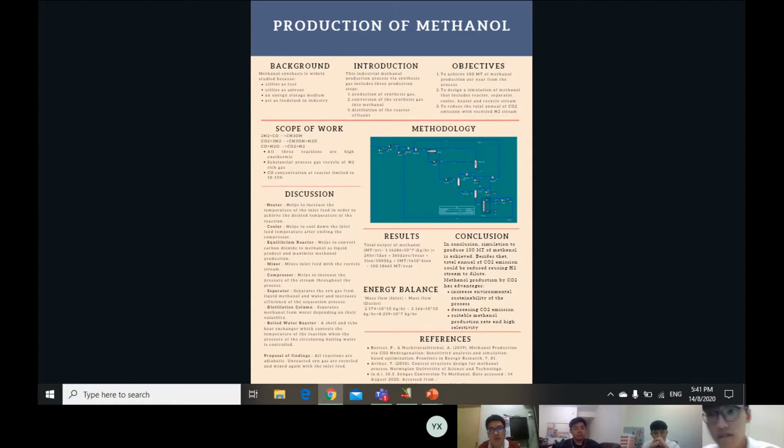The conventional gas phase process carries out the conversion in a reactor at high pressure. Substantial process gas recycle of hydrogen-rich gas moderates the temperature rise across the adiabatic reactor. Carbon monoxide concentration at the reactor inlet is normally limited to about 10 to 15% after dilution with recycled hydrogen.